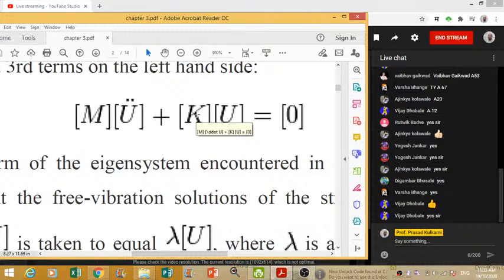So the natural frequency of the component can be improved by adjusting the mass and the stiffness of the component. I am repeating my statement. Listen, because it is important to avoid resonance failure. Natural frequency can be improved by adjusting mass and stiffness. As I told you, root k by m is the formula.